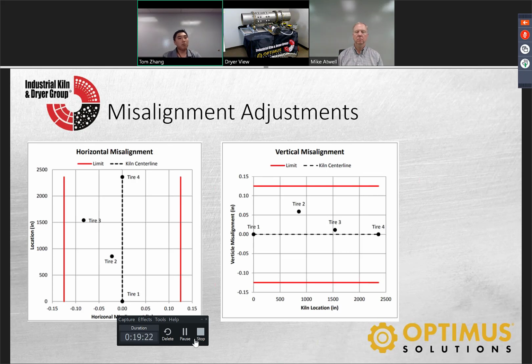We've also started modeling misalignment in our FEA models and have shown that this hits close to the 3,000 PSI limit on the shell. So we have now verified that you really want to stay within this from a fatiguing standpoint, or ultimately a circumferential crack over time. When you're within this limit, an eighth of an inch is not much. It's tiny for what, a 10-foot, 15-foot, 25-foot unit? It's pretty small.